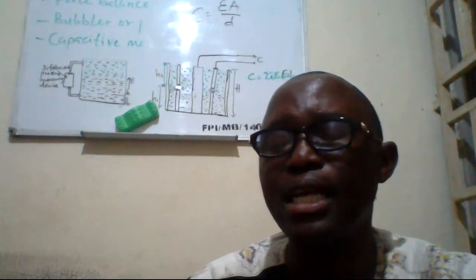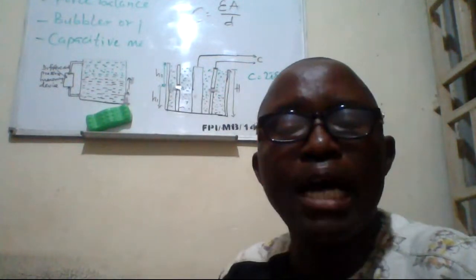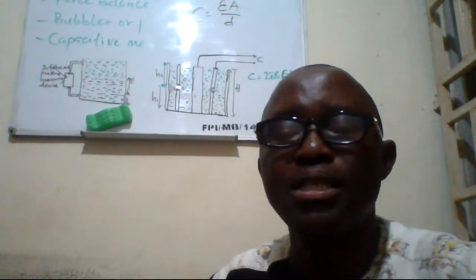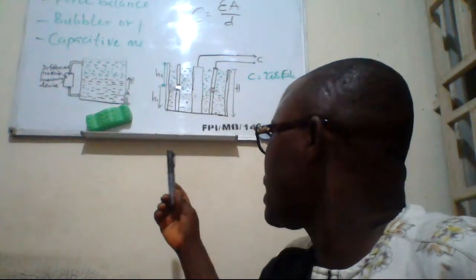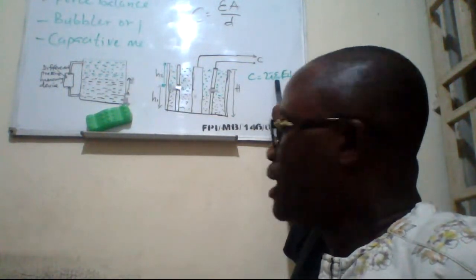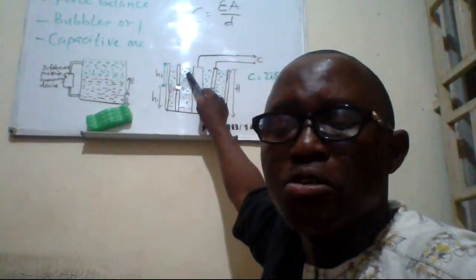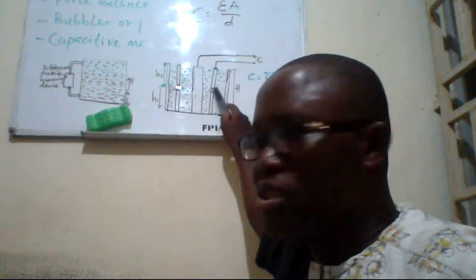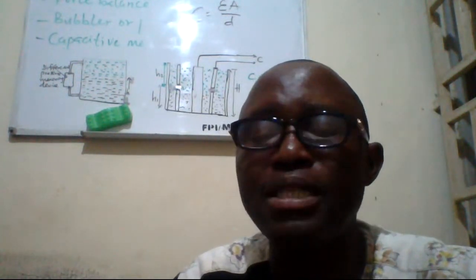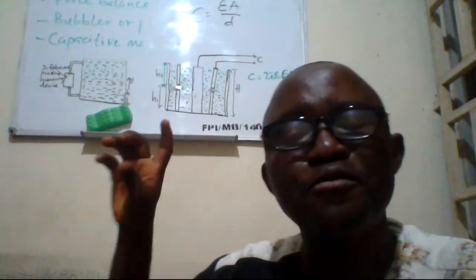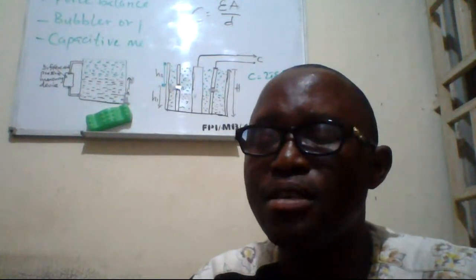So when you check that, you see that there are levels, height for liquid, height for vapor. And so from that formula, height for liquid can be made the subject of the formula and calculated when other parameters such as the permittivity epsilon naught, permittivity of liquid, permittivity of vapor, and the radius inside the tank are known. So that is how it works. So with the value of the capacitance measured, then from that formula, the total height of the liquid can be calculated. As simple as that.